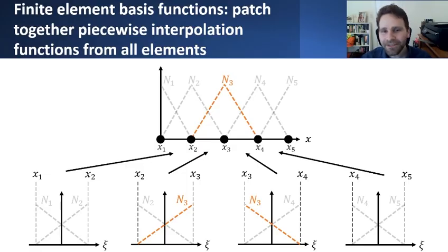So those are some interesting observations and some nice properties that enable a few other interesting characteristics of finite element basis functions. But the main thing is that we can recognize that these basis functions are really constructed in this piecewise fashion. Over each element, we define these local shape functions, and the basis functions is really the terminology reserved for the shape functions put together and stuck together in this global coordinate frame.